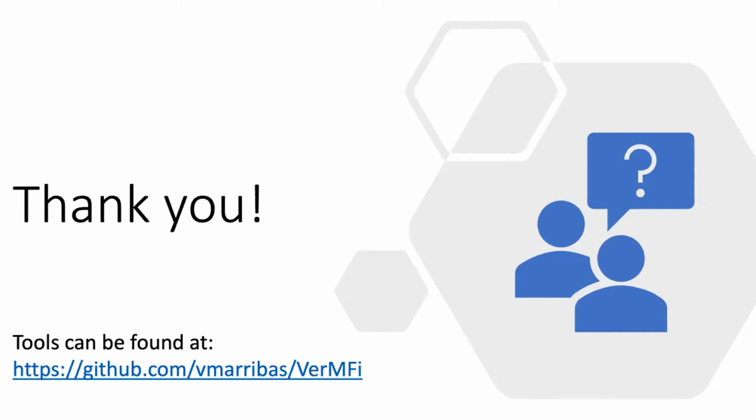For example, the first tool that I presented, towards side channel analysis, is more limited in the sense that it's a very specific check that we do. We also do the uniformity check, but that's a bit more limited. Those checks are usually meant for TI implementations. But for example, the non-completeness property, we have seen that most, if not all, algorithmic countermeasures need this property. So our tool would serve for this property, for all these countermeasures. But maybe countermeasures at the gate level, which do not have this glitch propagation such as LMDPL, this tool couldn't help there because we may not need to check non-completeness. So in that sense, it's limited as far as the necessary property needed.